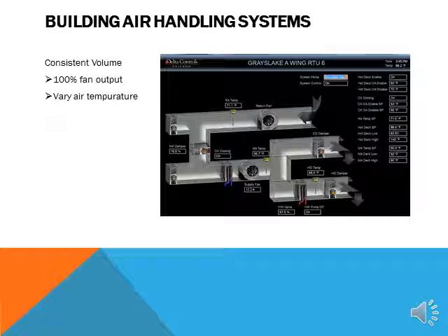There are no dampers out in the building system other than balancing dampers to maintain the proper amount of CFM in each space. What happens in this type of system is the fan runs, and if we're in heating season, we put heat into the air to maintain a discharge hot deck temperature, or we provide cooling to the cooling coil to provide a cold deck temperature. In this case, you see the two ducts, one with heat, one with cool, to provide whatever the system needs through each of the dampers. It then will go out to the space and maintain the temperature.